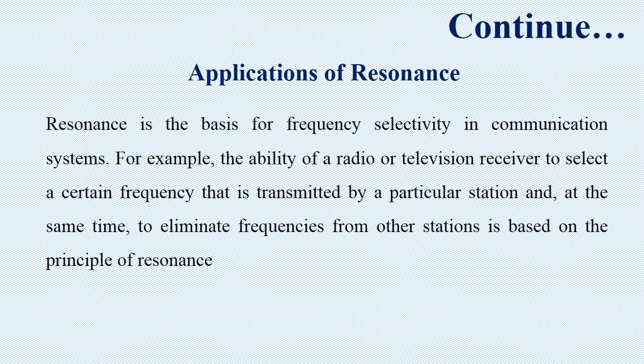This principle is used in radio communication for selecting a particular channel. Let's say you have an FM receiver and you want to tune it to one particular frequency or channel. Now let's say you want to change the channel. We change the knob of the receiver. Effectively we are changing the capacitor value in the circuit.